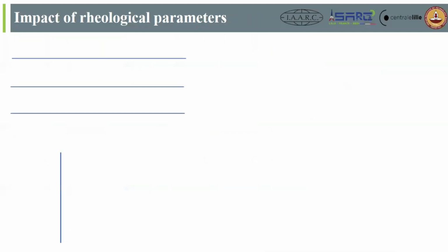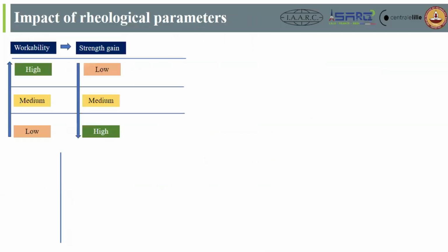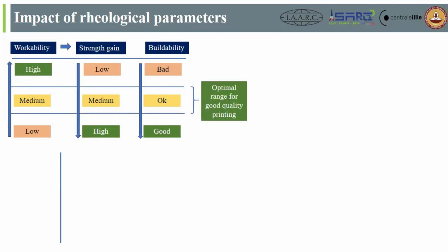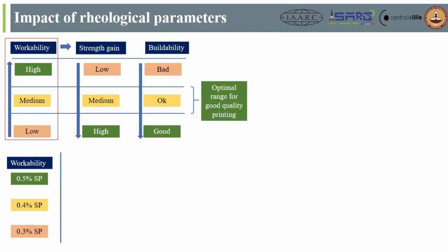Coming to the next slide. For the experimental prints, as I told, buildability is directly dependent on the strength gain of the concrete within a certain time. So to vary the strength gain, I changed the workability values.